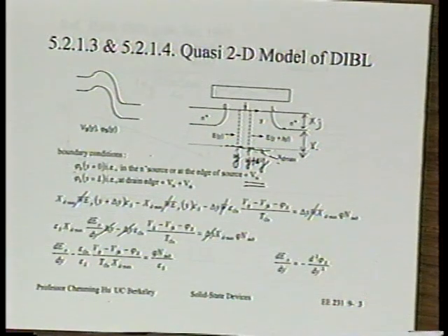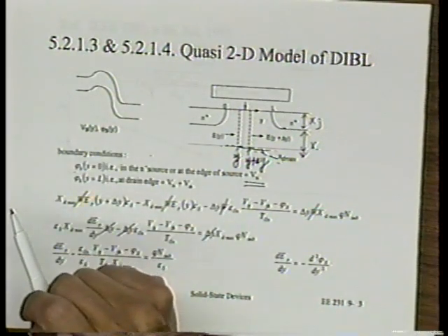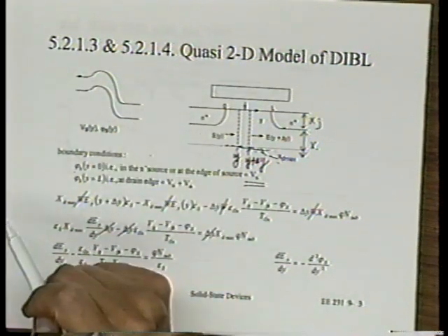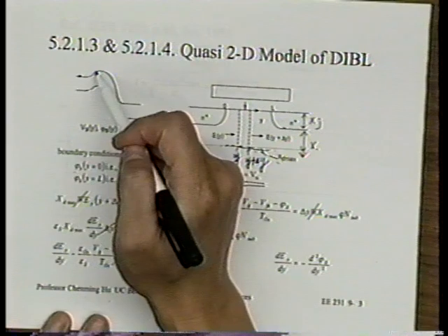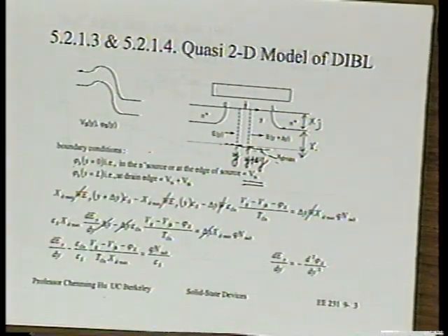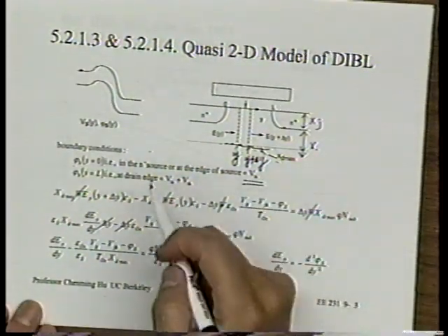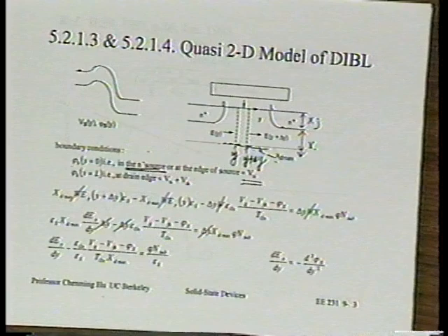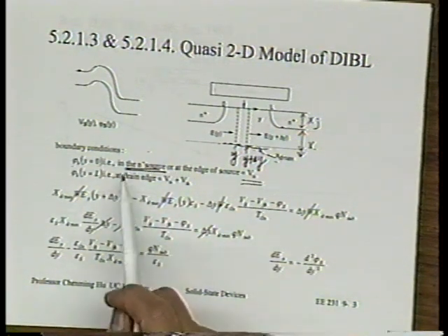Now, when we do that, we automatically are telling what boundary condition we're using. We're using a boundary condition that at the source, it's 0, right? Inside the source is 0. Therefore, inside this channel would be VBI. Actually, I beg your pardon, I took it wrong. I'm sorry. Okay. In the N plus source, here's the emphasis, I forgot. We take phi s. All we know is phi s. We're asking what is phi s in the N plus region of the source.